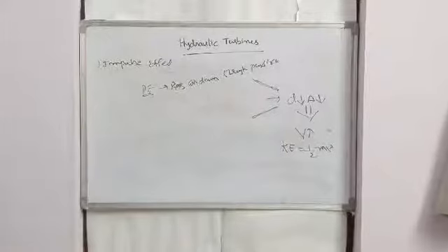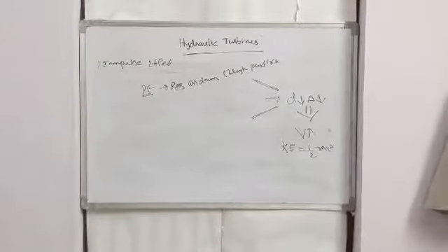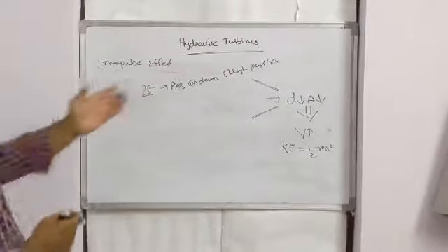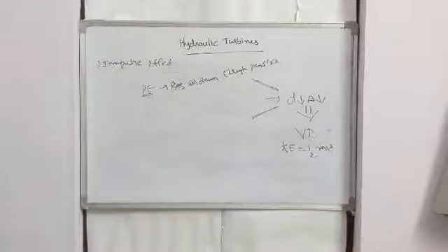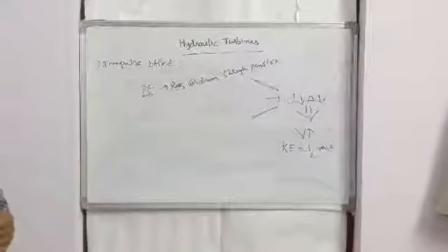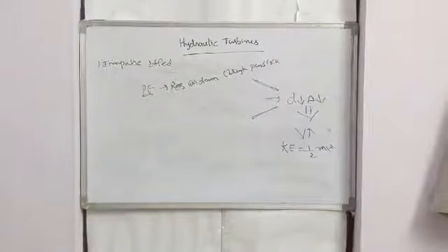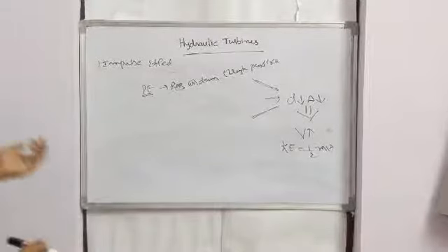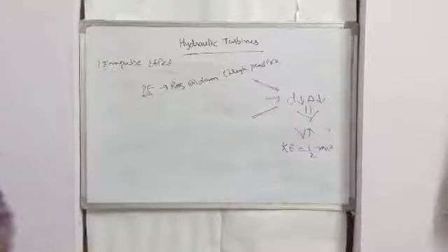So the available hydraulic energy, the potential energy, is first converted into kinetic energy by means of an efficient nozzle. The high velocity jet issuing from the nozzle then strikes a curved or a series of suitably shaped vanes, fixed vanes on the periphery of the blade or wheel.